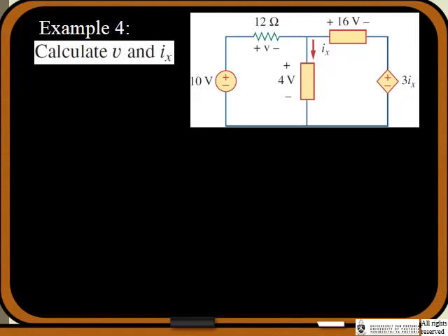So now we're going to see if we can use Kirchhoff's voltage law and Kirchhoff's current law. If we take this loop, this mesh, because it's just one, a loop with no other loops inside of it, I've got the 10 volts, that's known. The voltage V is the one that I don't know. And then I've got 4 volts here that I do know. So for loop number 1, we can write down the equation that we're looking for.